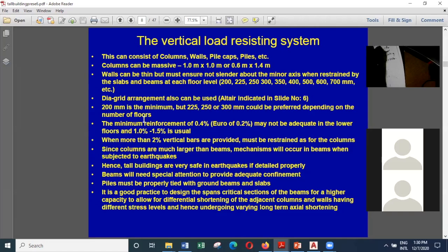The link requirement for columns is, generally we have a general rule, something like, the link spacing can vary between 8 times diameters to 20 times diameters. And early in the British codes, we used to limit it to 12 times the diameter of the smallest vertical bar. All this is to make sure that when the column is heavily reinforced, which means the column reinforcement will be in compression, the reinforcement will not buckle. To prevent buckling of the reinforcement, you need to have a certain restraint for the reinforcement.